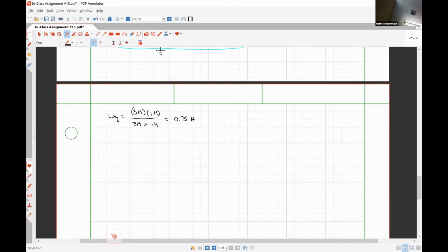So that means that my 10 volt source is going to be off. So that's why I replaced it with a short circuit. Here is my 4 ohm resistor. Because we're looking at it during the transient condition, that means that we're looking at it while the switch is closed. So there's my closed switch. Here is my 6 ohm resistor. Here is my 12 ohm resistor. Here are the terminals where we've been connecting our equivalent inductance. So those are the terminals that we're going to be looking in through. Here's my 4 ohm resistor. I have an open circuit where my current source was.